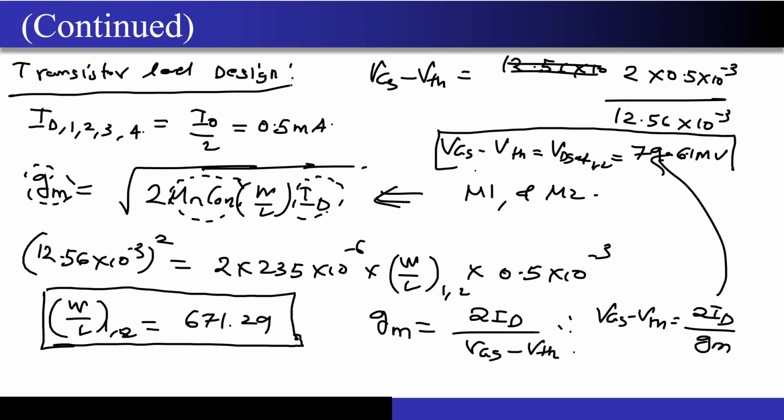And remember, if any value comes out to be this small, this is the minimum VDsat that you need to maintain. Now while doing the practical design, you will add some margin on top of it, maybe 30-40 millivolts, and then you will assign the VDsat. So if this is 80 millivolt, then ideally you should assign a VDsat of 120 millivolt. Some headroom will be there, and across the PVT variation, even if there is a threshold voltage variation of 30-40 millivolt, your transistor will still remain in saturation.